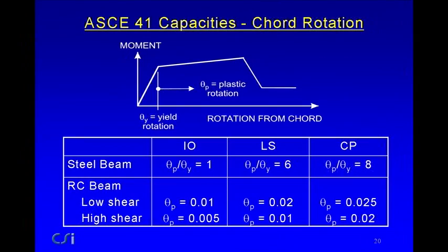And it does vary with axial force, as we can talk about later, but ASCE basically does this for all beams, regardless of the span to depth ratio and things like that. And this is just an example that ASCE 41 in its current form is really a little crude. So this is a one-size-fits-all type of capacity.